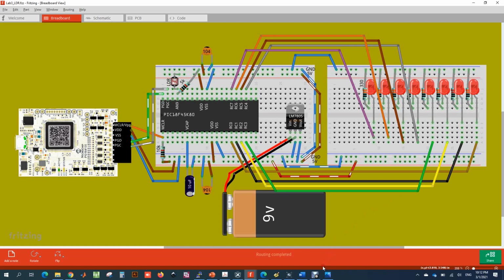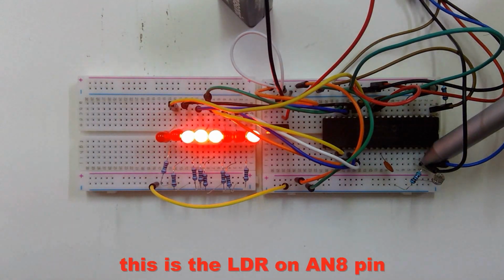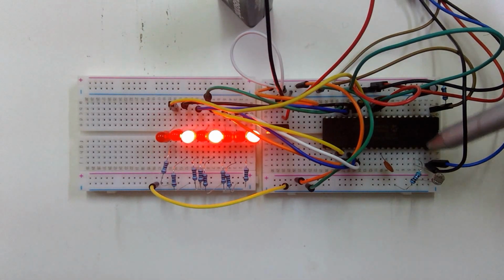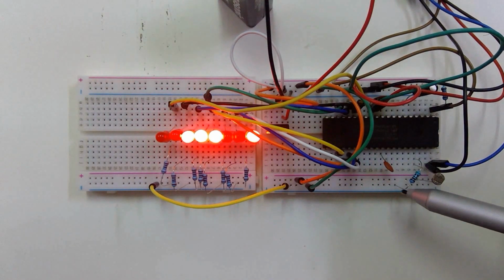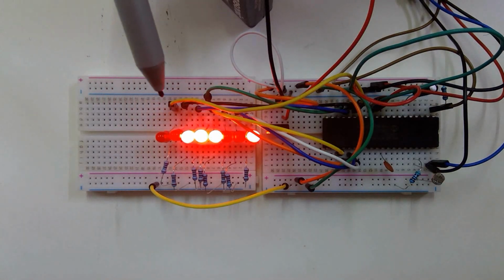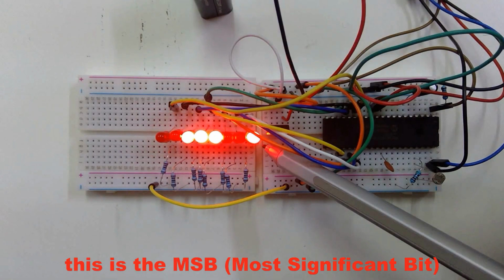Now let us see the working on the actual breadboard. So this is the actual working on the breadboard. The LDR, you can find it connected here. This is on the AN8 pin of the microcontroller, and a 5 kilo ohm resistor connected to the ground, and the LEDs, they are showing a binary number. So this is the LSB, and here this is the second bit.